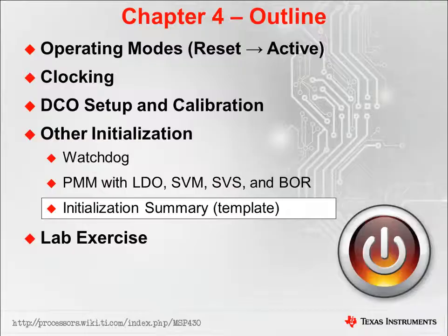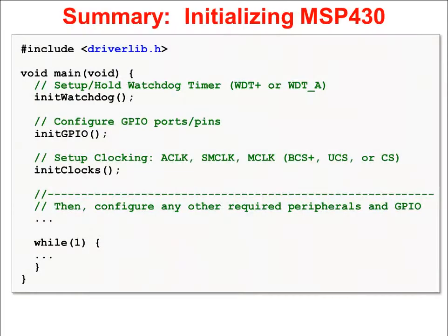Our final initialization summary. This is very simplistic to kind of drive home the concept that at the beginning of main, there's some things we need to set up. We need to initialize our watchdog, we need to initialize our GPIO, and we need to initialize our clocks. Now there are a number of other peripherals you might need to set up as well,